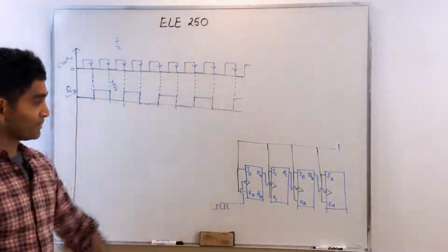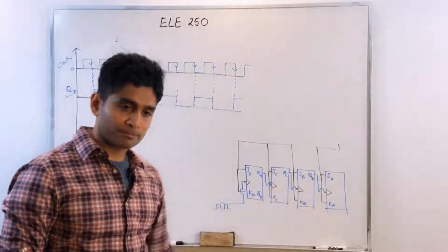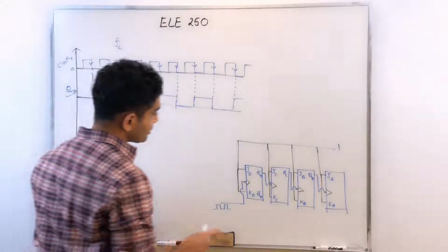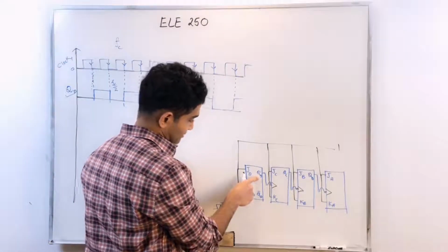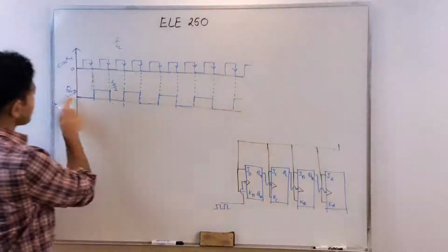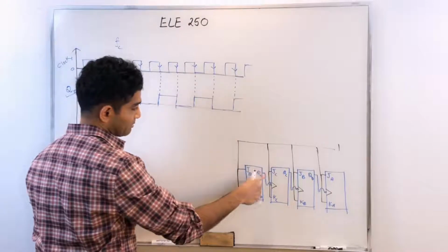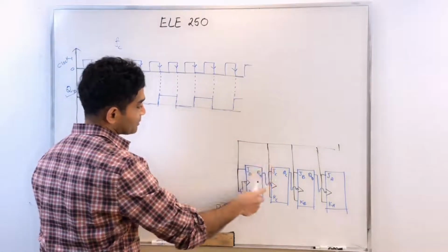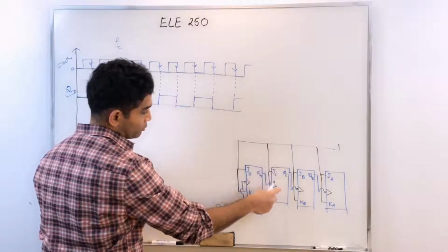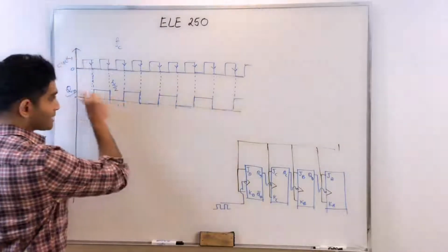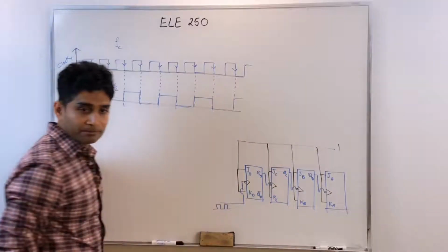Now what about QC? If I want to plot QC, now for QC, my QD is the clock signal to QC, right? My QD is what is being applied as the enable input of my QC flip-flop. So basically this is functioning as a clock to my QC.